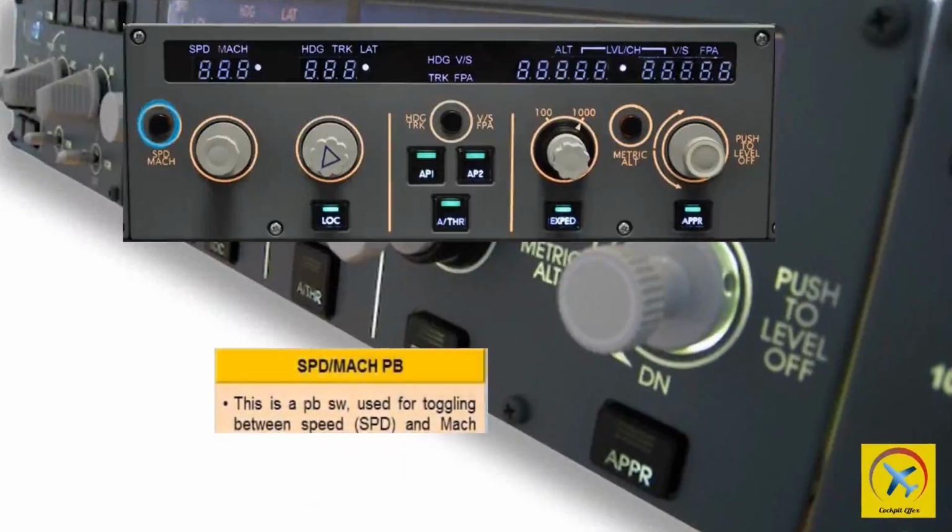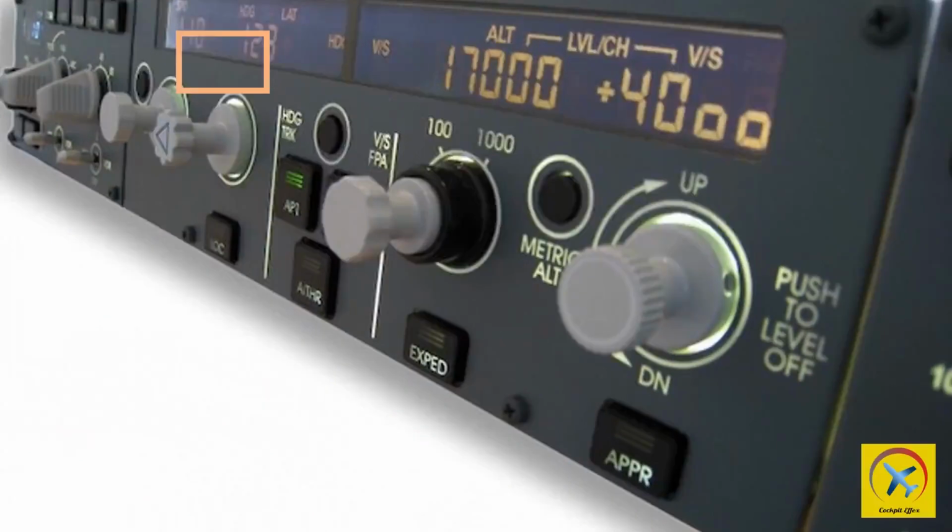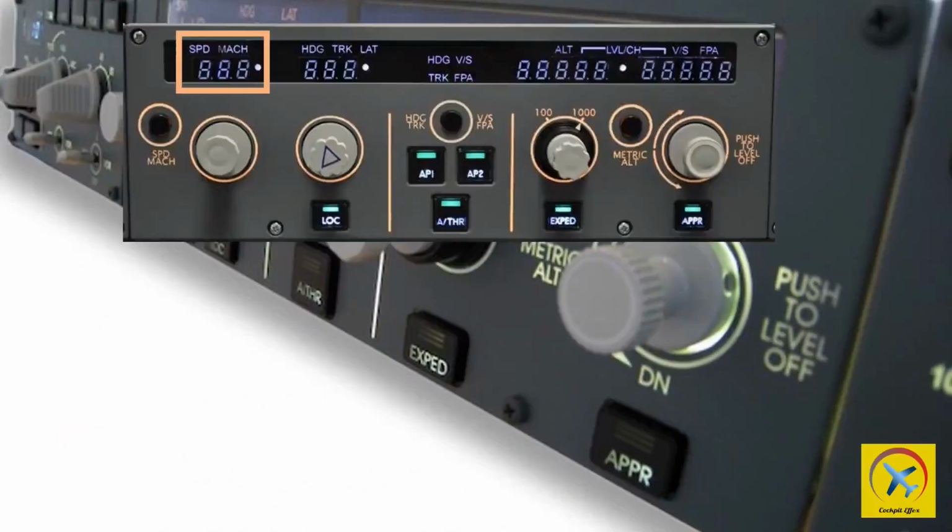The speed or Mach number button when pushed, changes the value in the speed or Mach number window from airspeed to Mach, and vice versa. The speed or Mach number window displays the selected speed or Mach number. When the speed selector is pushed, FMGS managed speed engages, the managed speed light illuminates, and dashes appear in the speed or Mach number window.